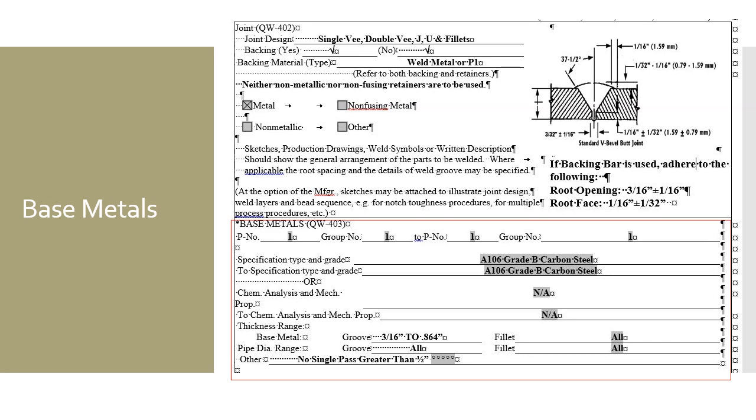But I've reviewed weld procedures and said, no, dude, you can't weld that with this. Well, yeah, I can. It's a P1 material. And I tell them, look at the way your weld procedure is written. It's written so that you can weld A106 to A106. If you want to rewrite your WPS, feel free to do so. I'll accept it, but you need to widen that up and get rid of where it says A106 to A106. I don't know why you'd include that, but sometimes guys do when they're writing them, and sometimes it's a mistake. They think they have to be specific, but no, you just need to put the P number on there. And if it's impact tested, then you've got to put group numbers on there.